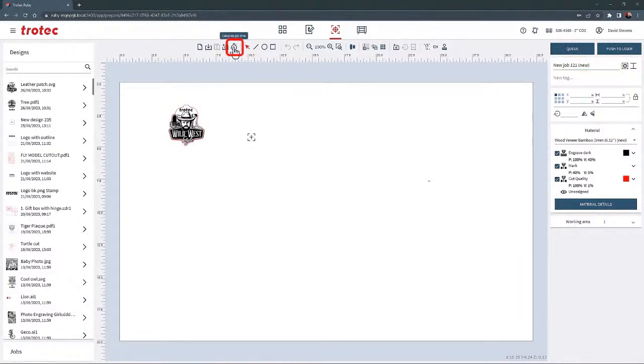The clock icon on the toolbar calculates the job time. The time given will change based on what material parameters are used. Once pressed, the time will briefly show on the bottom right side of the screen, and this time will stay paired with this job showing on the Produce screen when the laser is ready for processing.